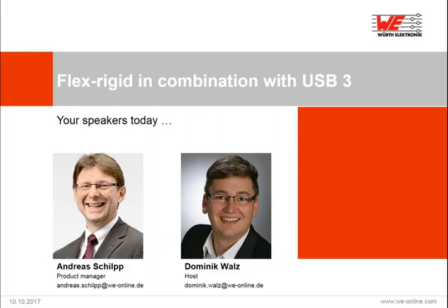So the question is about the combination with which rigid material we can get a good performance. USB 3 still works pretty fine with standard FR4. I don't know an application using USB 3 which is based on PTFE material or other mid or high performance materials. That's only needed for really big PCBs.